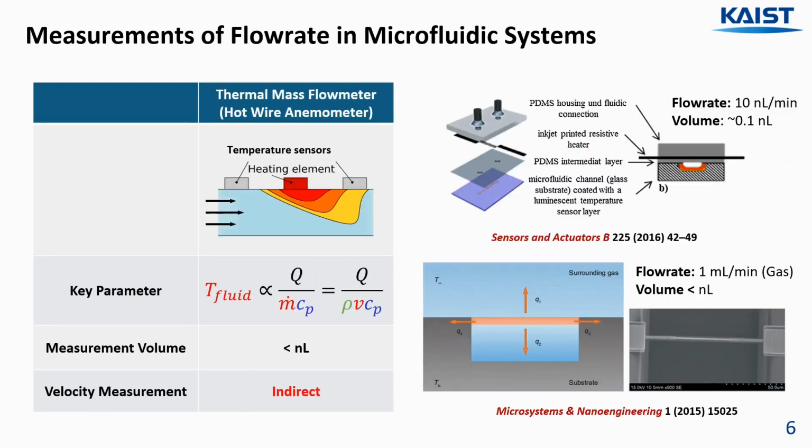Thermal mass flowmeters operate by electrical heating of a tiny wire inside the flow stream, and measure the cooling effect of the flow on the wire. They have drawn attention due to their high spatial resolution down to microscale characteristic length and maintaining high accuracy at low Reynolds number, even with gas flow measurement. Still, application in liquid flow measurement within microchannels is somewhat limited owing to the dependency of measurement on fluid properties and the difficulty of integrating fragile structures into liquid flowing channels.